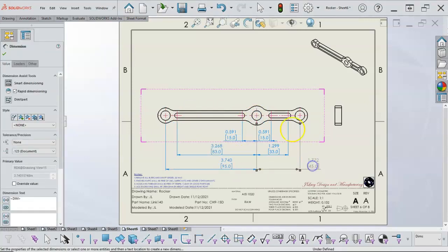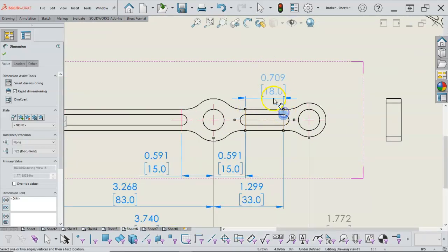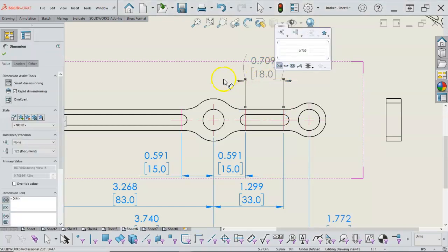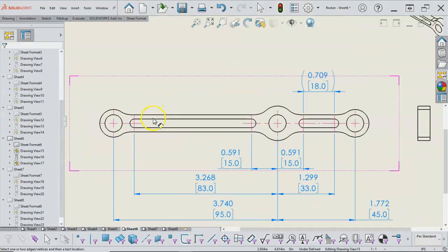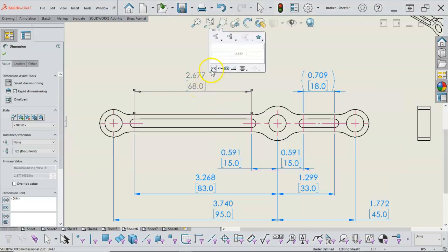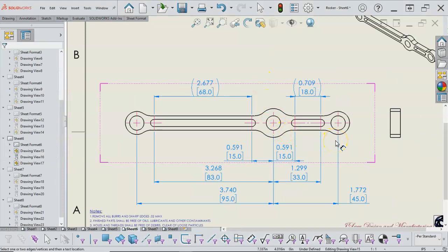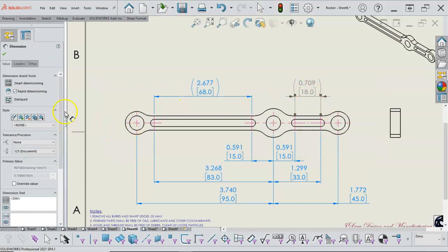I can have reference dimensions. Zoom up so I make sure I'm picking correct. And with our little pop-up, that parentheses is right there for reference, and that'll help a little bit with inspection, but really the machining manufacturing, I'm going to do better with those numbers. And realistically, let's see, because I went to the center marks, I'm not going to get the overall.